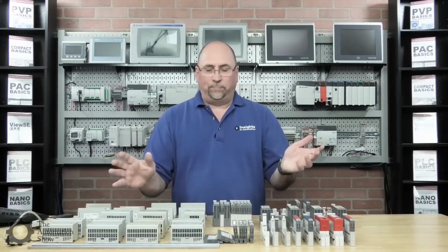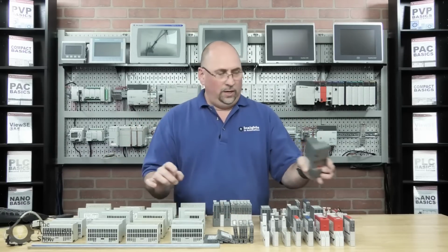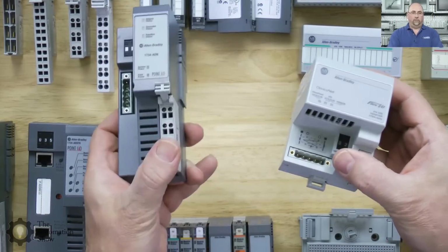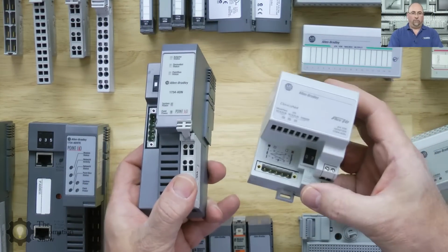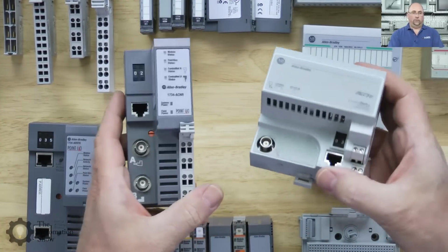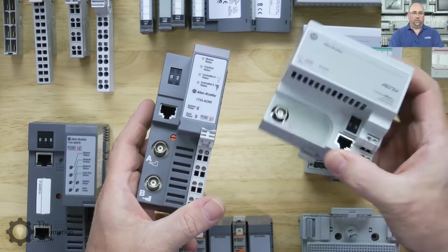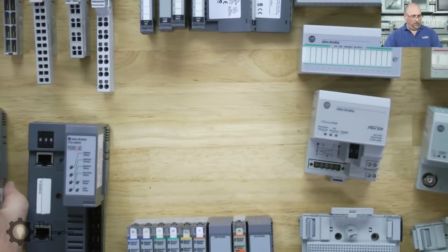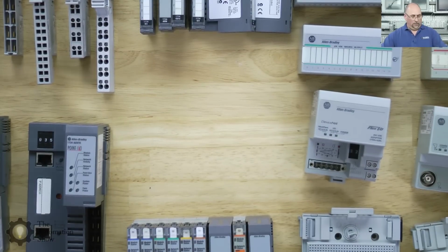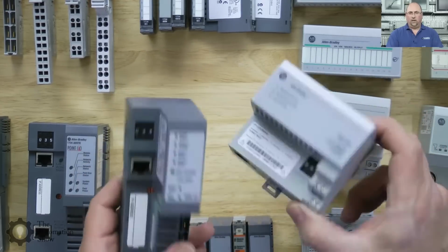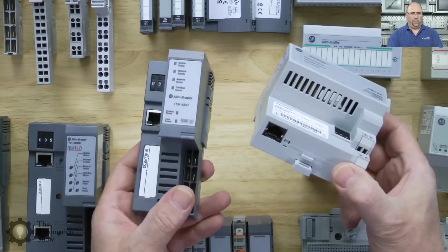many applications. And finally, both lines today support DeviceNet. So here we can see the DeviceNet adapter for Point-IO and for Flex-IO. They both support ControlNet. Okay, this is only a single non-redundant adapter, where this is a redundant one. And Ethernet. Ethernet's what most people are using today. They also both support Profibus DP.